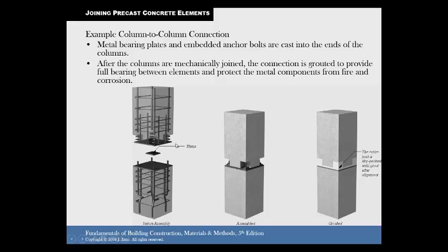Welding is actually a lot of times stronger than the steel itself, or definitely stronger than a bolted connection, if it's done properly, of course. And then you can see how they stuck them together. This one does have a few bolts in it. Probably it's bolted and welded. And then they'll put some sort of grout or something in there to cover up those, so it looks smooth.